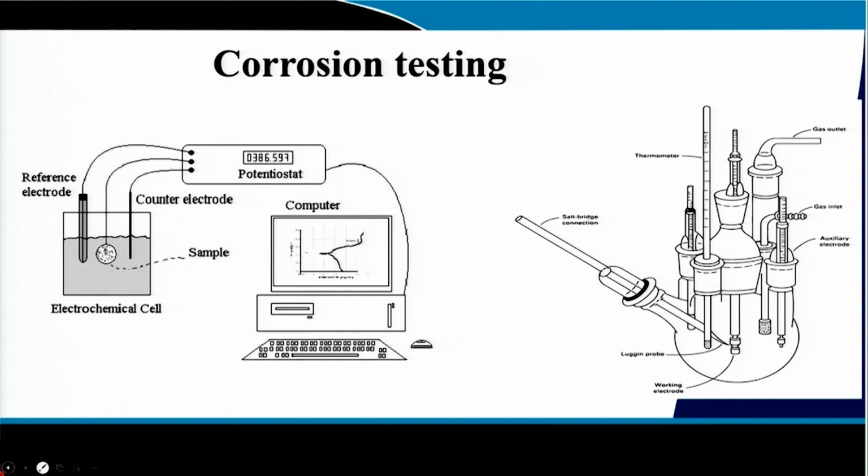In this particular test you use a 3 electrode system, where your working electrode is kept in between the counter electrode and the reference electrode. For the reference electrode you can use standard AgCl as well as standard calomel electrode, and for the counter electrode you can use platinum. Your component is actually in between. You just keep it for a while so that the component surface remains in equilibrium with the solution.